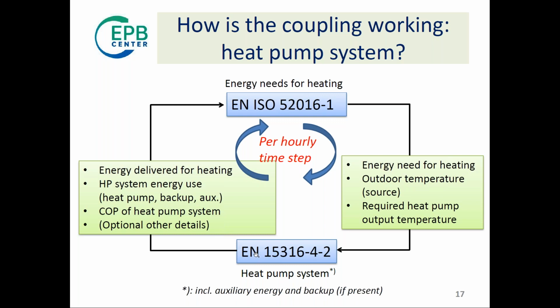And then the heat pump performance is calculated, and as an output of that, fed into the energy need calculation for that hour is the energy that is available for heating, and the heat pump system energy use, and the COP, the performance of the heat pump system, and also optionally other details can be transferred from the one to the other.